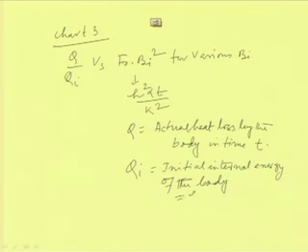and that is equal to rho into Cp into V, where V is the volume. So, rho Cp V is the mCp, rho into V is the mass, into Cp is the mCp into Ti bar. Ti bar is the reference temperature with respect to the environmental temperature, that is T infinity. So, Qi is the initial internal energy of the body with respect to the environmental conditions, and Q is the actual heat lost by the body.